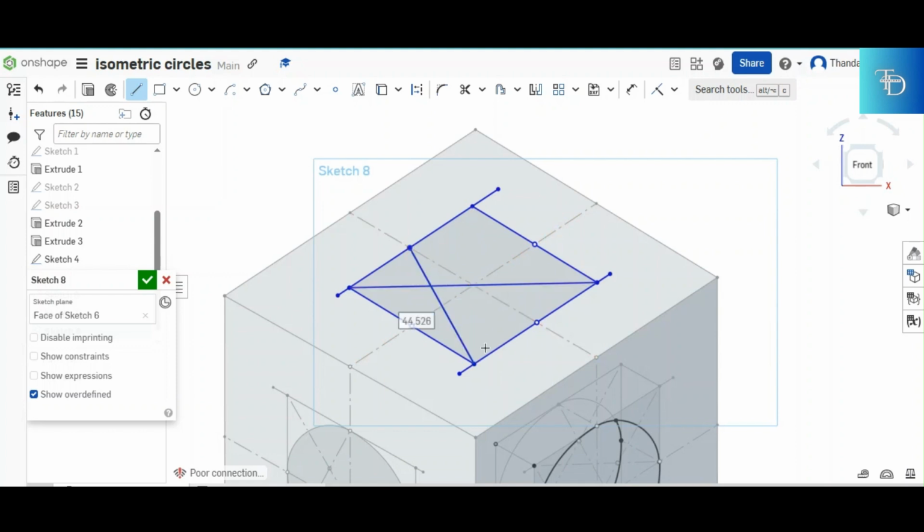If it goes to the center, it goes to the center. Next thing you do, you highlight your center points for your compass right there and there. And then the last step, you produce your what? Your isometric circle. There you go. Now we've completed the base of the circle.